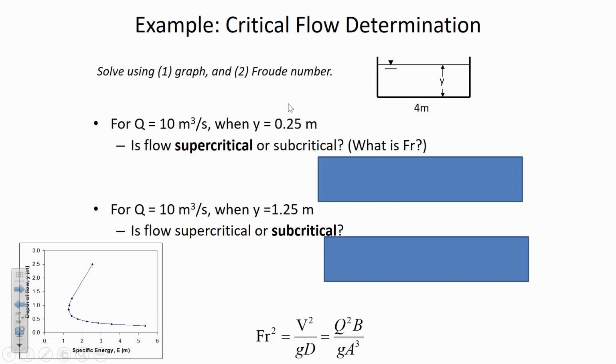All right, so this is a refresher, when we have the shallow depth, so the depth is less than the critical depth. So the critical depth is 0.86. So when the depth is less than 0.86, is the flow supercritical or subcritical? I wonder why I bolded supercritical. Maybe it was a hint.